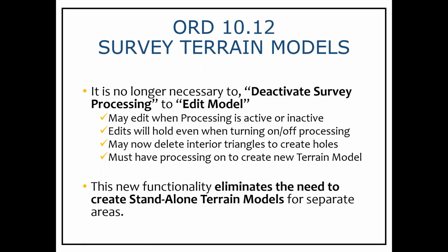So it's really important to know the difference between 10.10 and 10.11 and then 10.12. Okay. You also may now delete interior triangles to create holes. You could not do that before. Only exterior triangles could be deleted. You must have processing on, however, to create a new terrain model. This new functionality eliminates the need to create standalone terrain models for separate areas.